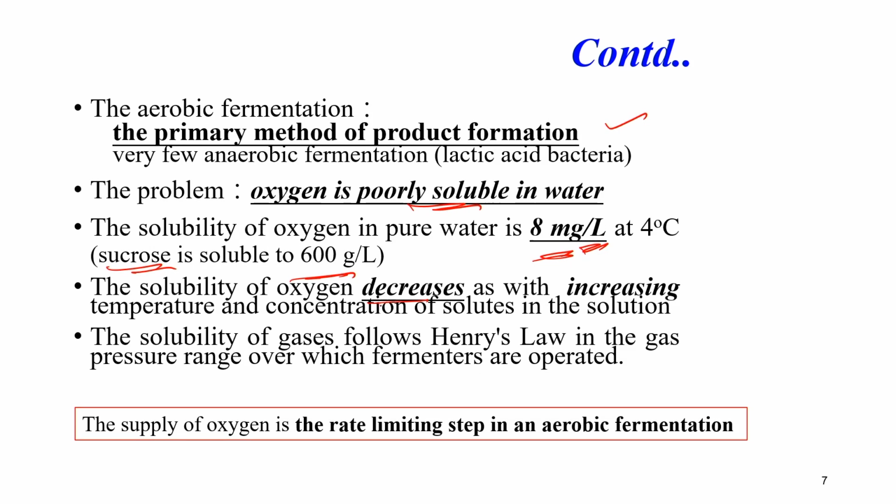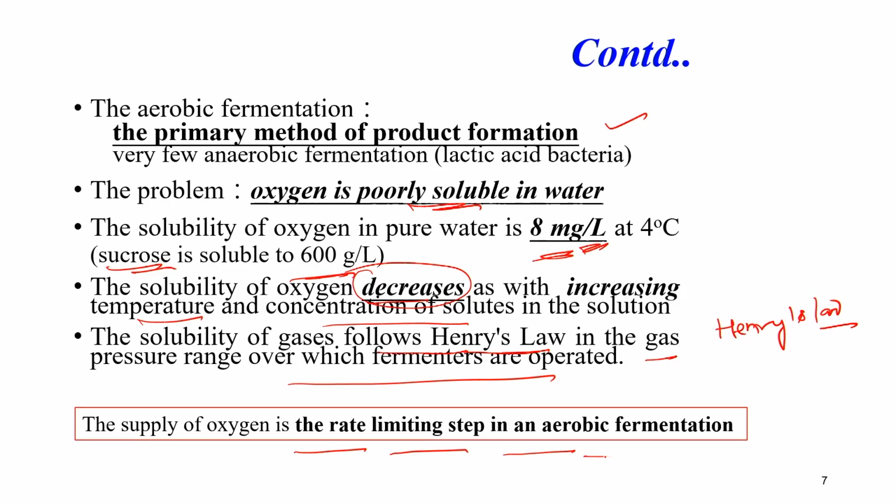Further, there are environmental factors, like increasing the temperature or concentration of other solutes, which further cause a decrease in oxygen solubility. We will see that the solubility of oxygen follows Henry's law. So, we will quickly have a look at what is Henry's law. What it highlights is that the supply of oxygen is a rate limiting step, particularly in aerobic fermentation.